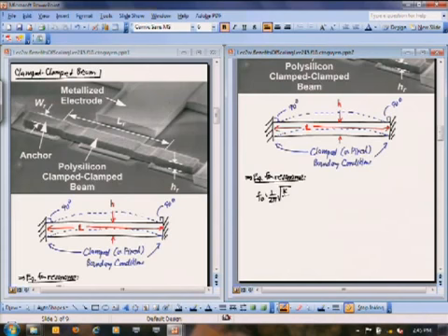But when you do the whole differential analysis of dynamic equilibrium for this, which is considerably more involved than for that string that we just did, this ends up being equal to 1.03, which is the number you get out of that full analysis. I won't tell you exactly where that number comes from here yet, times the square root of Young's modulus. Well, let me not say what these are yet. So the square root of a quantity E divided by rho times the thickness H divided by L squared,